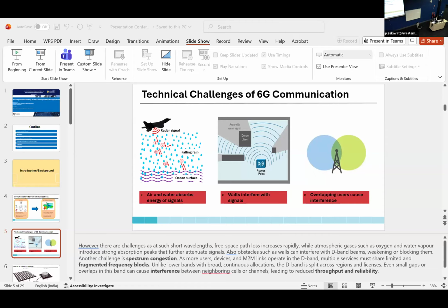So my aim is to create a reconfigurable band stop surface to dynamically tune the stop bands in the D band spectrum using PIN diodes, hence blocking of narrow frequencies which could be unwanted in 6G communications. I will first discuss earlier studies to show how my work extends these previous developments.